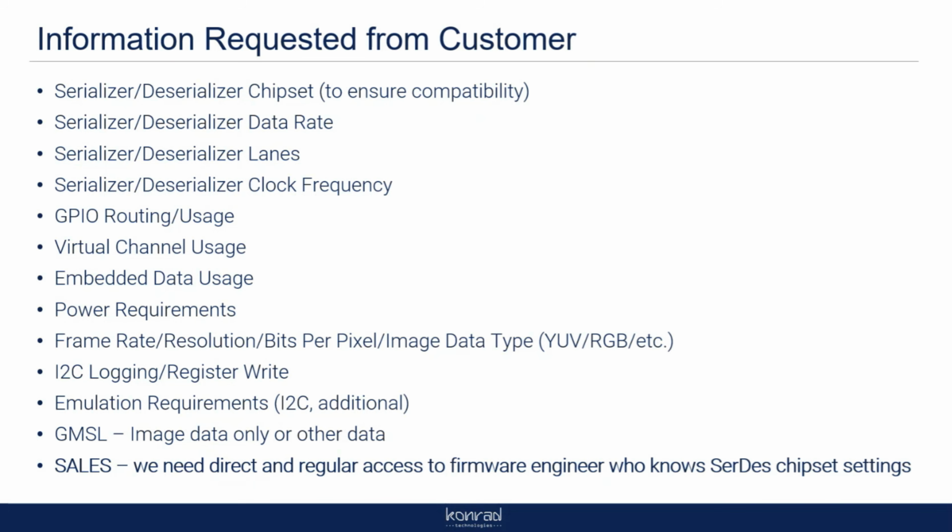And a lot of these ECUs are running Linux of some flavor. So sometimes it's opening a command prompt, getting on the device, like SSHing into it and saying, hey, check streams. And it'll be like, yep, okay, or not. Or can we pull a log from their ECU, right? So it's all that information. And so sometimes trying to work with an OEM is difficult because they're getting ECUs and cameras from suppliers and they don't have access to this. If you're at a supplier that has this information, it's probably a lot easier for you to do the application.